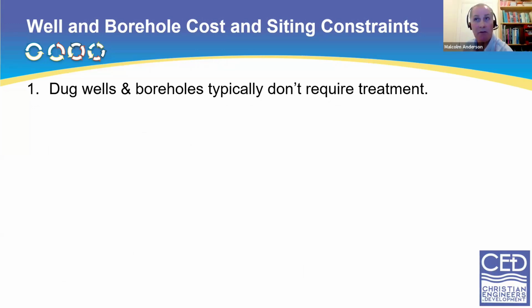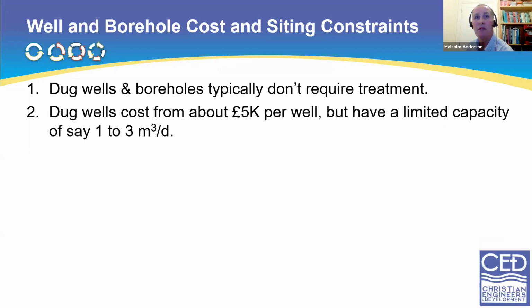Dug wells and boreholes typically don't require treatment because normally the water is of drinking water standard. However, there's a caveat to that, because especially with dug wells, you've got somebody inside the well digging it out, so it will be contaminated by dermal contact, and it will need disinfecting before it's put into supply. Similarly with boreholes. In terms of cost, dug wells cost about £5,000 per well and have a limited capacity of, say, 1 to 3 meters cubed per day.